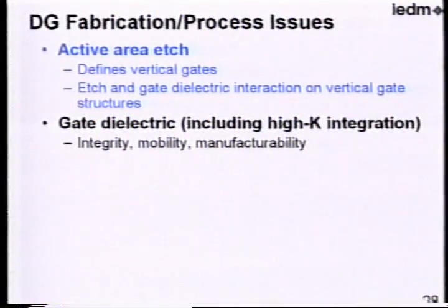The scaling of the gate dielectric may be relaxed a little bit, but it will continue on down, and then you'll have to integrate high K into this, and that integration is over a fin or a step, which means conformality and other issues at that interface. You've got corners now, and at the corners the VT may be changing a little bit, which has to be considered in these devices.